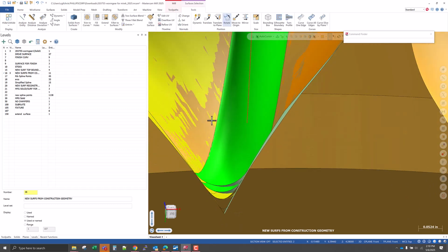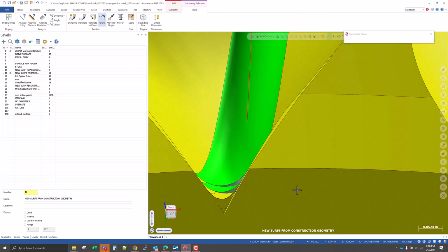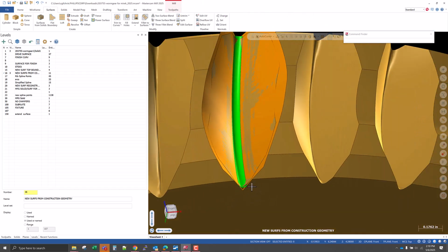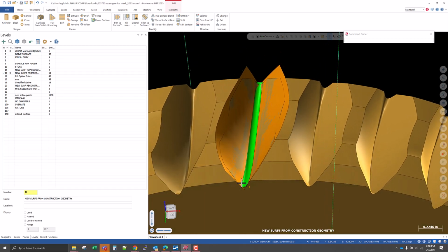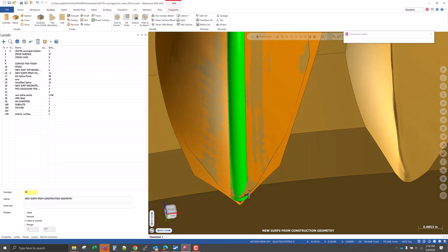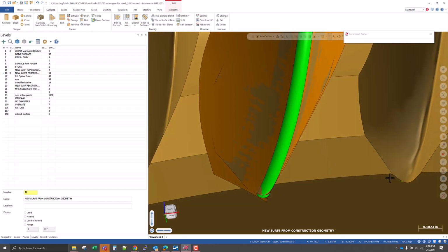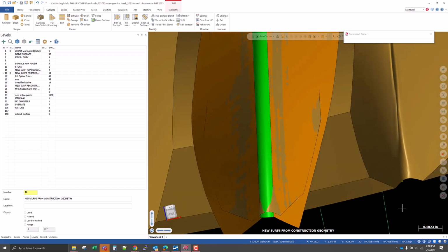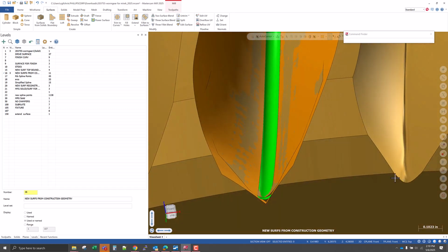So, I think this kind of 35 thou radius is pretty good. I mean, we could go in there with something slightly smaller. It's going to dive in a little bit more in the corner, which is probably really what they want. I mean, honestly, having this bigger radius at the very edge, to me, reeks of a modeling inaccuracy.